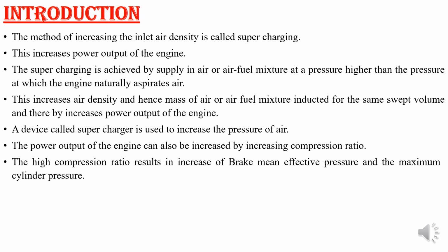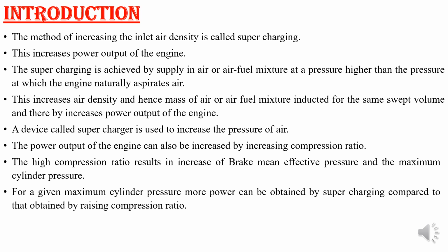That means we want to increase the power output, so whatever maximum pressure you get while supercharging should increase less than your brake mean effective pressure. That is the meaning of this sentence. Whatever pressure you are giving to your cylinder, that is air, whenever combustion takes place, the combustion pressure should rise less than the brake mean effective pressure.